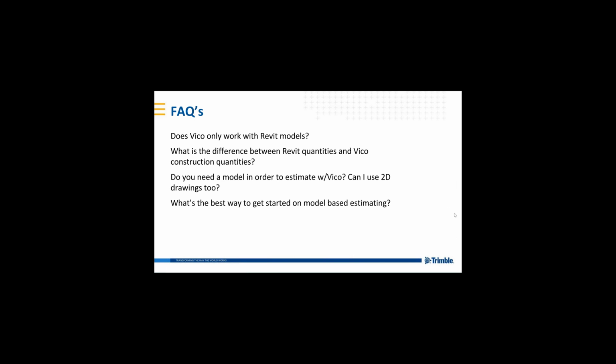From one slab, I can derive finishes, I can derive all my volumes and my square footages, and there's just so many ways to leverage it. So I say start small. Get any model that you can get your hands on, bring it into Vico and start playing with it, just looking at those construction caliber quantities. Then even click off a 2D takeoff over a model, and compare what the quantity Vico produced versus what you clicked off, and I think you'll find it's usually exactly the same.